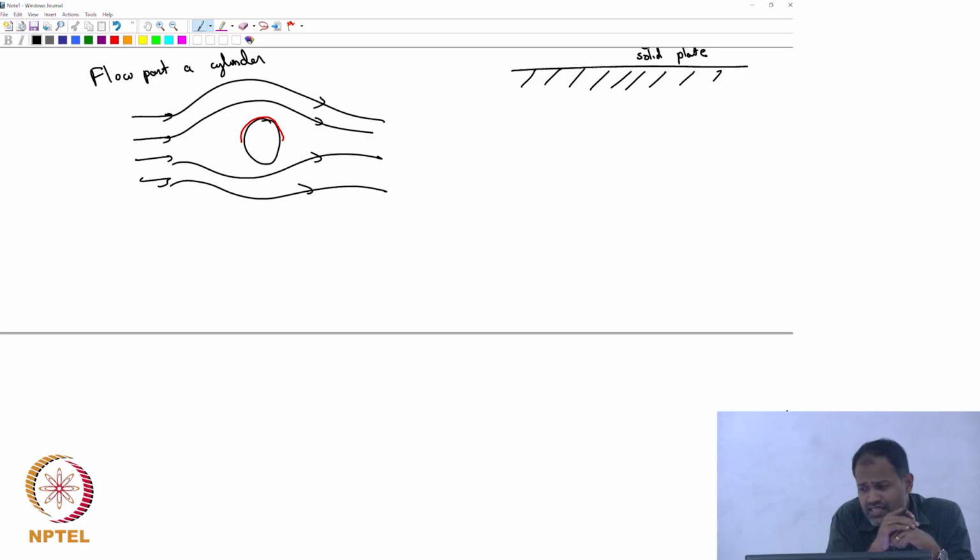Second is that we will also use this concept to explain flow separation. You remember in one of the classes I was talking about expanding sections and so on, and I said, yeah, the flow could get separated. The analysis of the boundary layer will actually tell you where the flow separation happens, or why it happens, and so that's another thing that we are going to look for.